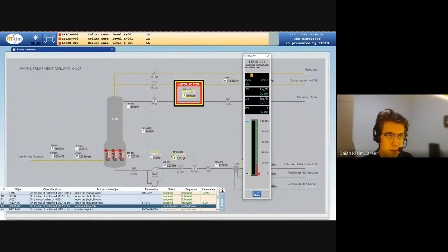So let's click 50. And the next mistake is trying to adjust a new set point in manual mode or manipulate the PV. PV is a parameter, the current parameter.